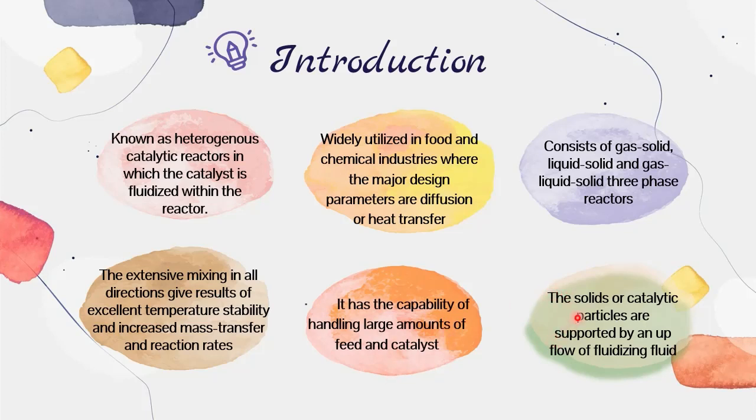Lastly, the solids or catalytic particles are supported by an upflow of fluidizing fluid, which means fluidization occurs when small solid particles are suspended in an upward flowing stream of fluid. This reactor also provides easy loading and removing of the catalyst. This will be very advantageous when the solid bed must be removed and replaced frequently.